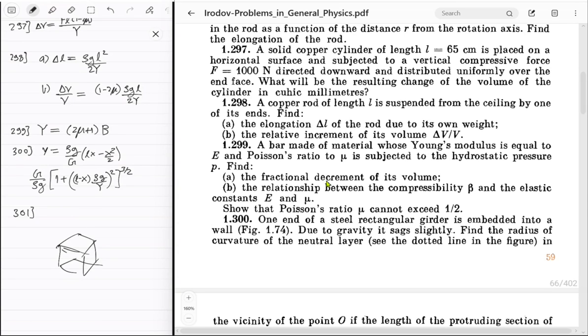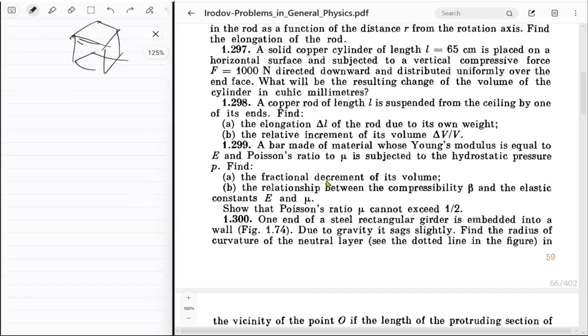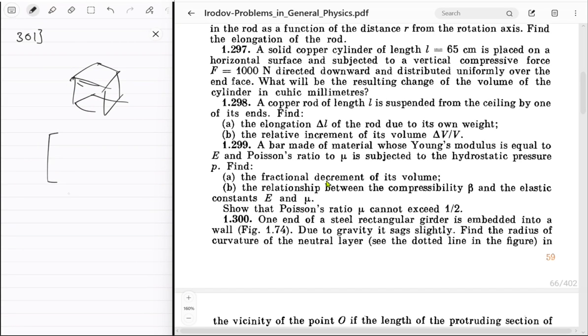I did that, and that's how I got this relation, which is completely incorrect, because you also have to account for the stresses from the other directions, since Poisson's ratio causes changes in your strain in a particular direction. Across the x-axis, you also have to account for the pressure along the y and z axes, because those also matter. So this is not how it should be. Instead, you will have to use this, the general Hooke's law, though general Hooke's law also accounts for shear stresses; here it's a special case because there are no shear stresses.